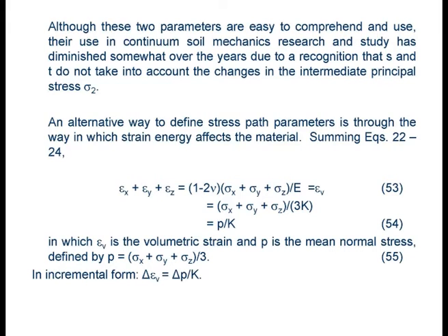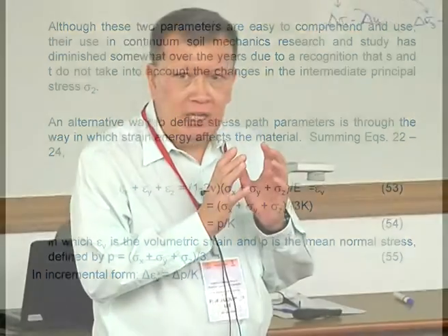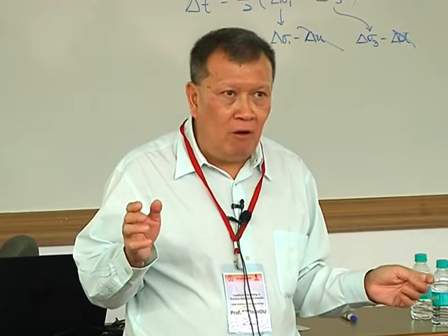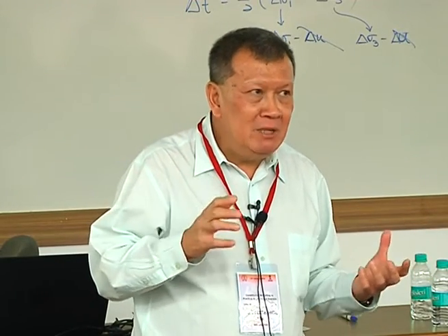In terms of constitutive modeling, it has one drawback. And that drawback is that if you look at S and T, the effect of the intermediate principal stress is not considered. It doesn't appear at all. So therefore, there is something that is missing from there.